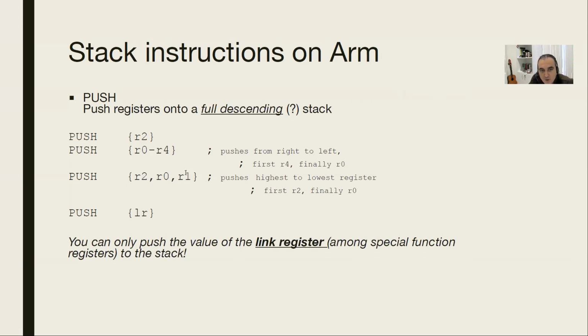Or you can do this. And be careful. If you use a dash, it is right to left. If you use commas, it is not right to left. When commas, it is from the highest to the lowest register: first R2, then R1, finally R0. Be careful with these rules, when to push which one.